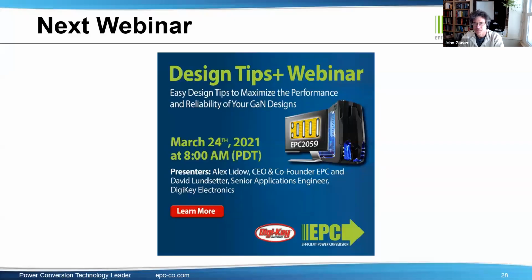Okay. All right, thanks. Next question is, what is an accurate method to sense the current making it to the laser? Oh boy, that's a good John question. And John, talk about some of the tricks you've used there. Okay, so our high power demo boards, we actually use a shunt, and the shunt is a lot of resistors in parallel, basically 5 or 6 typically, and they're small, 0402.